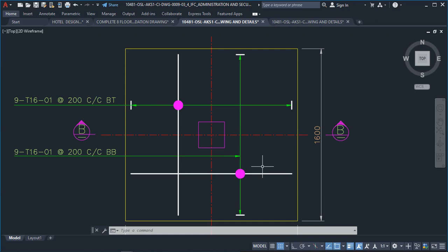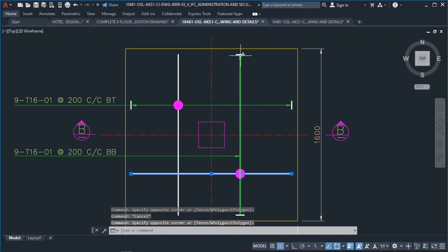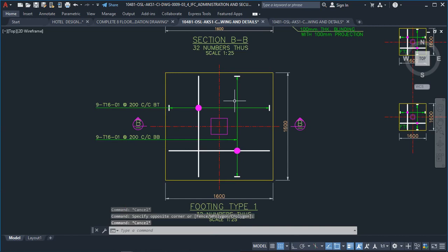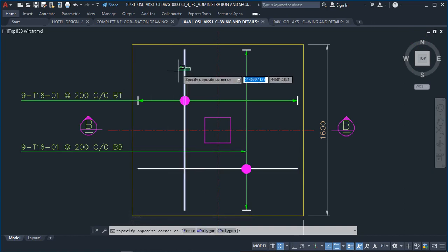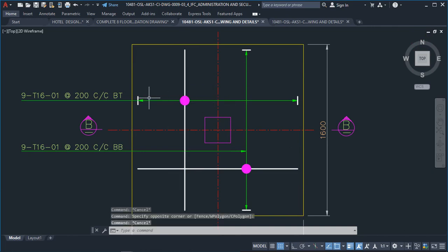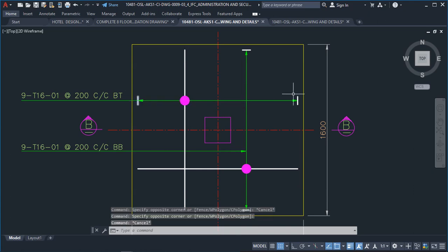So with this right now, anybody within your drawing, we know that with this arrow symbol here, you're trying to see that this reinforcement runs from this point to this point. Now, the same thing happens in this other direction. You also have to show how this other reinforcement is running. So you have to also offset your concrete cover and start from there, and then show the direction at which your reinforcement is going. So for this case, this reinforcement is going from this concrete cover to this concrete cover.